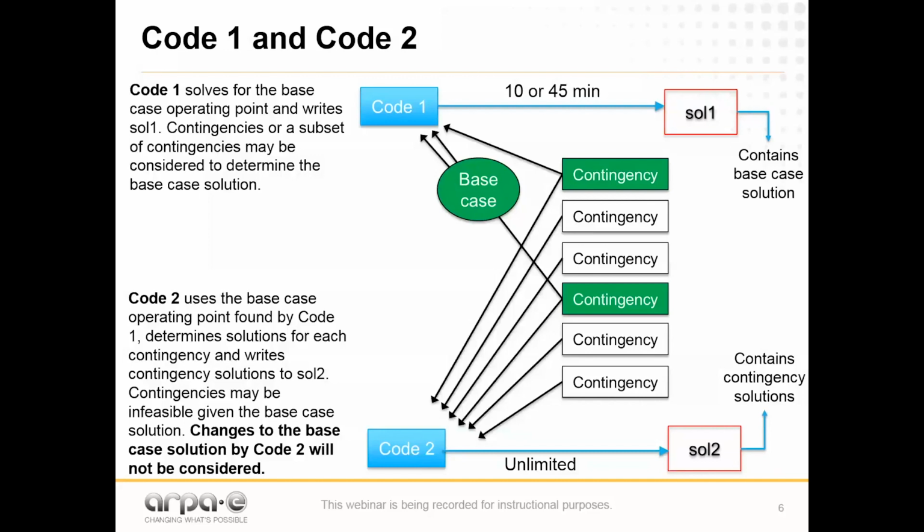Okay? Let me explain it in a different manner. Let's go back to my 1,000 megawatt case, which is what I'm expecting across the system. There's subset A of generators that respond but reach limits. Then there's subset B of generators that respond and follow their participation factor perfectly. Whatever amount of megawatts subset B needs to provide, delta K should adjust accordingly, such that the sum of the participation factors with the generation in set B corresponds to the needed impact associated to what they need to provide.